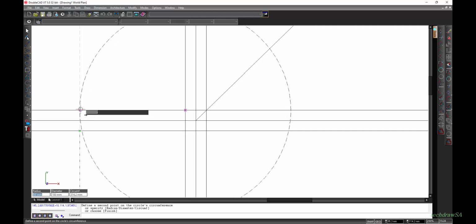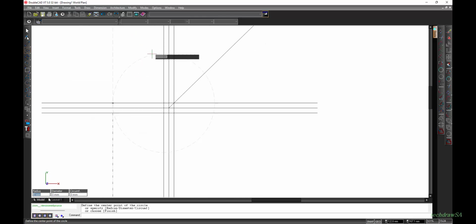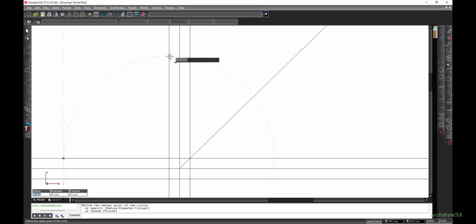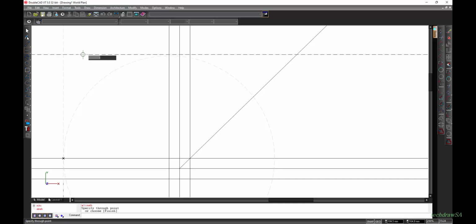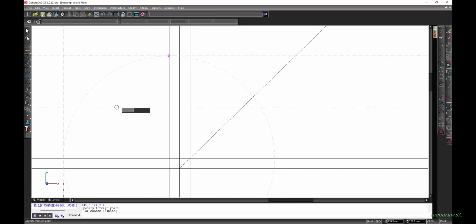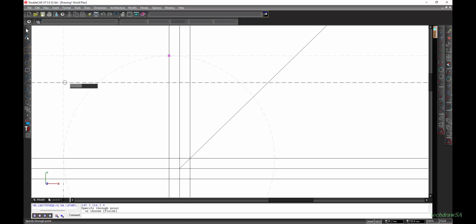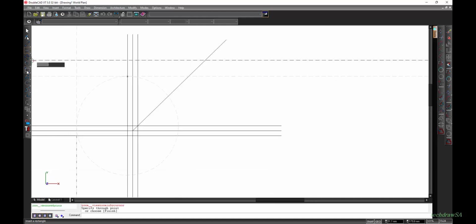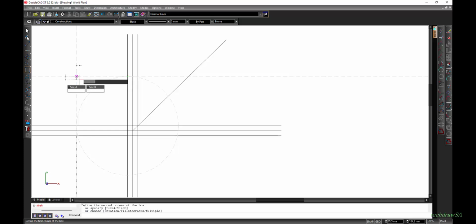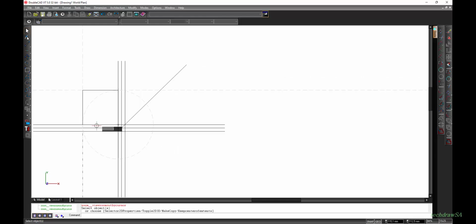You know that distance is 50, and you can click on it by snapping on it. And now you also have the reference point here at the top. So I'm going to select the horizontal construction line and snap to there. Now I have the shape for my top view. So with that selected, I'm going to use this rectangular box just for what it's worth. Click on that and then snap it to there, and there I have my top view.